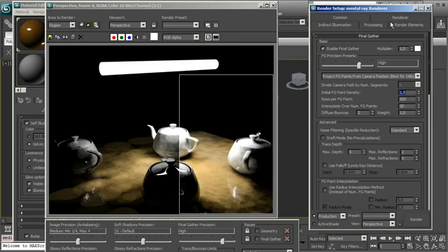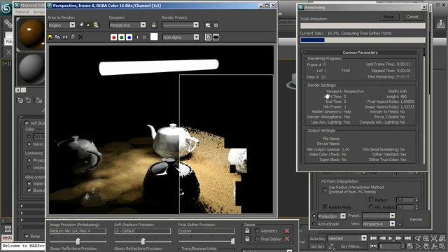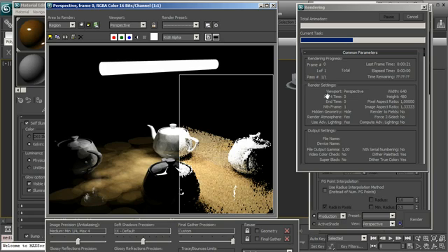So we can start, for example, setting to 2.0 the initial Final Gather point density, and 2000 the rays for Final Gather points, and we can use, for example, 150 the interpolate number of Final Gather points. And let's try to make a render test. It will be again slower than before, but let's wait for the rendering. You see that we have also the shadows for the mesh just using the Final Gather.